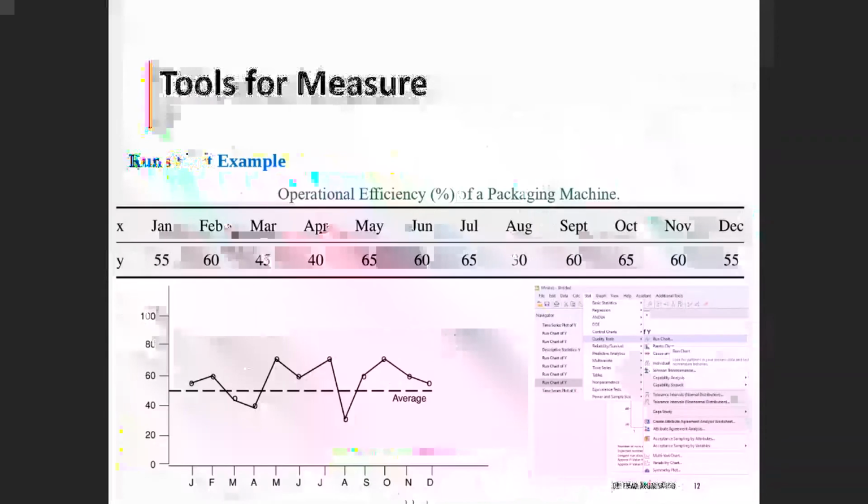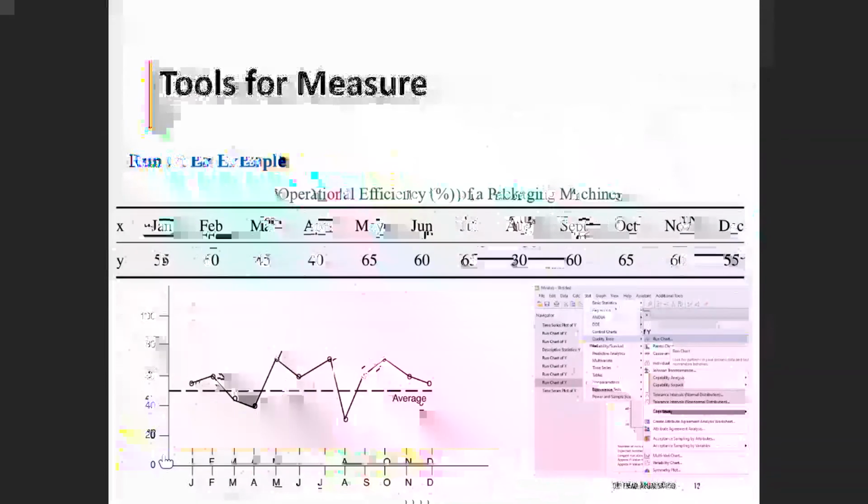As we saw here, it also shows you the average for the performance, but it doesn't tell you whether the process is stable or not. It doesn't give you control limits. In the control charts, we see lines for the control limits, and if any points exceed those lines, that means an out of control condition has happened, and you have to eliminate it, investigate, run the chart again, and see what the causes for that condition are.